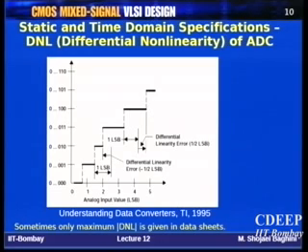What we look at is: if you are at this particular transition point, where is the next transition point? The next transition point, for example, is less than 1 LSB away. Here it is exactly half an LSB. Therefore, you have a differential nonlinearity error of minus 1/2 LSB.